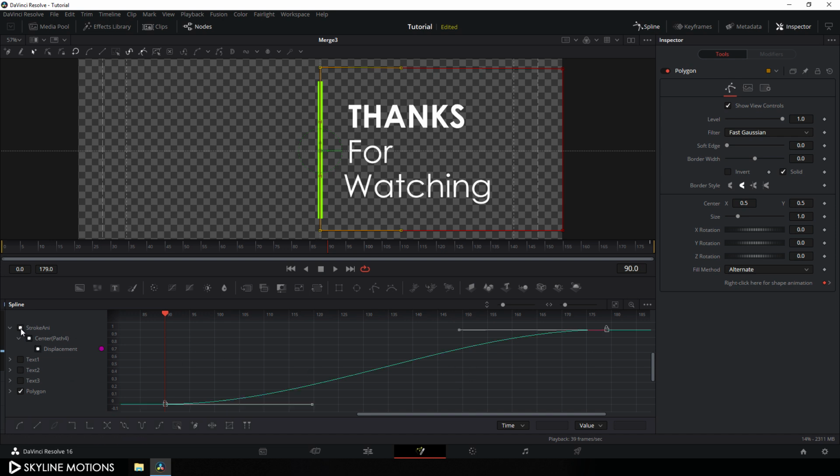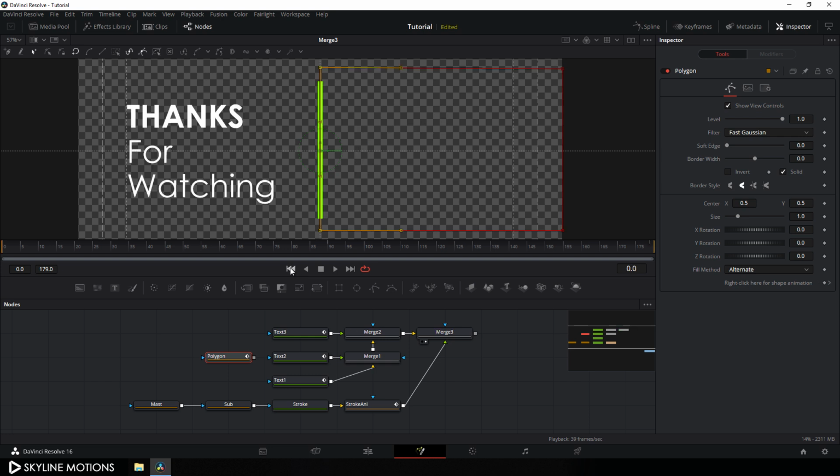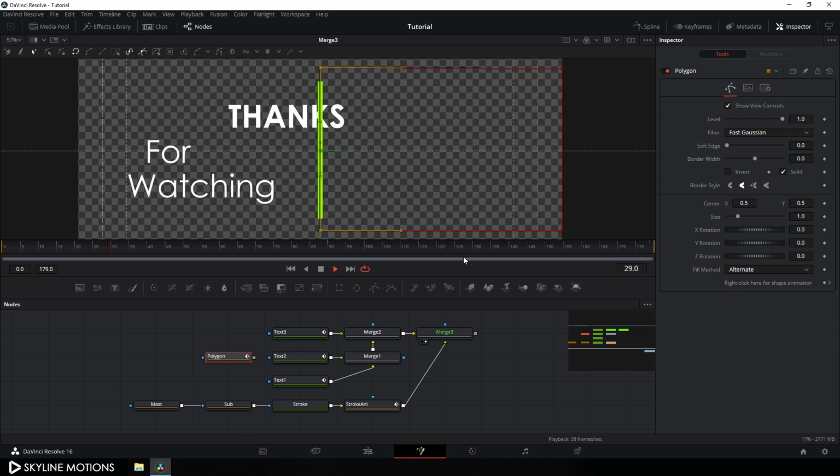So uncheck this stroke animation, and for this one just go to the end of this animation, because I'm going to keep this animation slower at the beginning and faster at the end. So hold this point and let's create this type of graph and do the same thing for this stroke animation. So uncheck this polygon and check this stroke animation, click on the fit button and create a smooth graph just like that. And go to the spline window, go to the very first frame of this animation. Alright, so now we have a smooth animation.